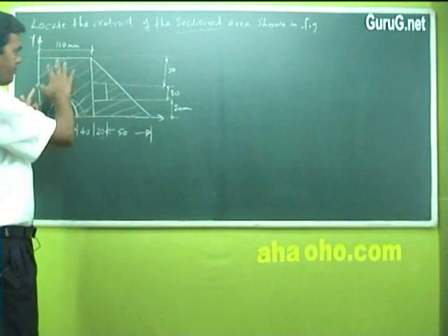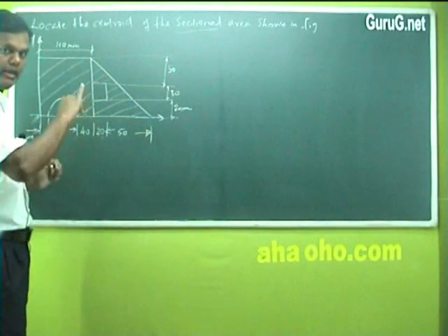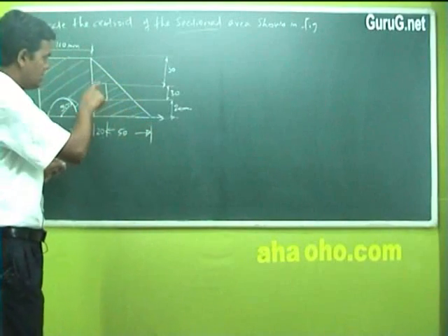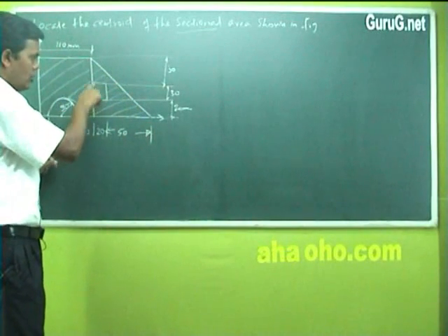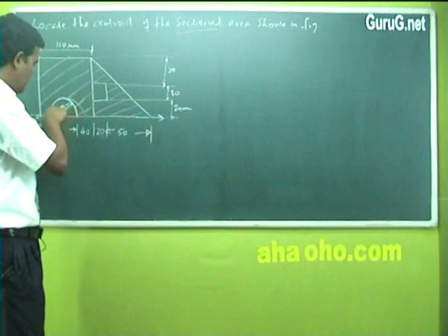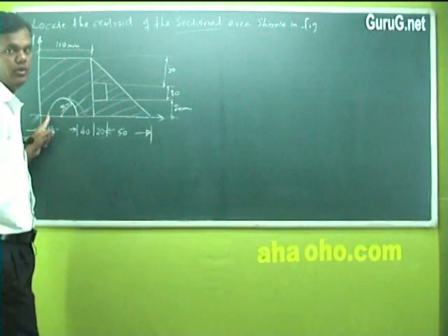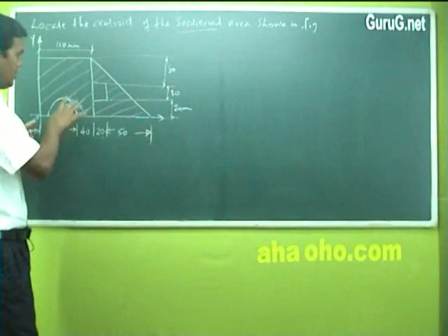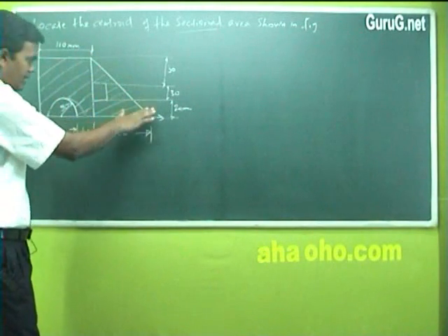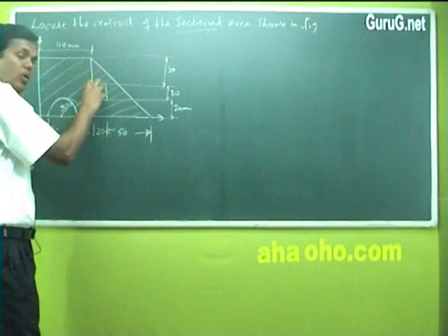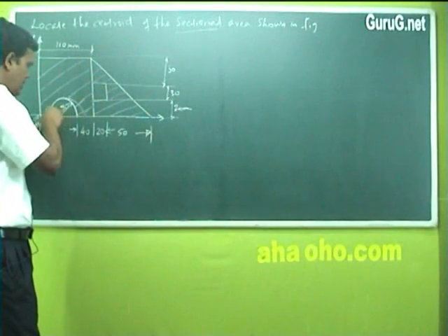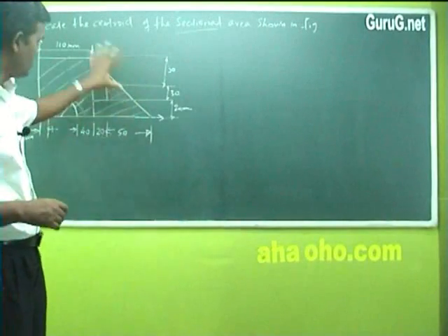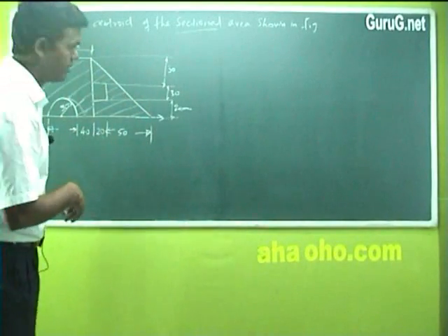Here, after calculating everything, the area, x and y values, you have to reduce the particular hole, that is this rectangle, and this particular semicircle value. Why? Because in the total body you have a big rectangle, big triangle, and there is a hole shaped as a small rectangle and a semicircle, which has to be reduced from the total area. That we'll see how we do it.